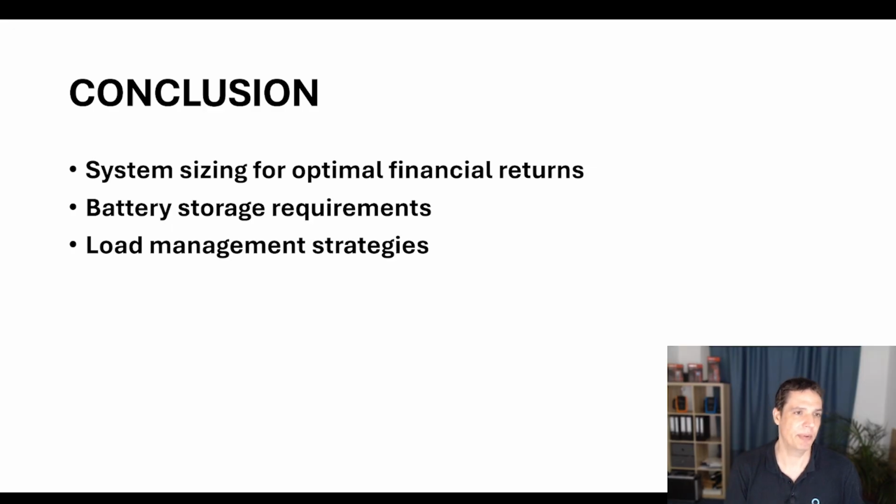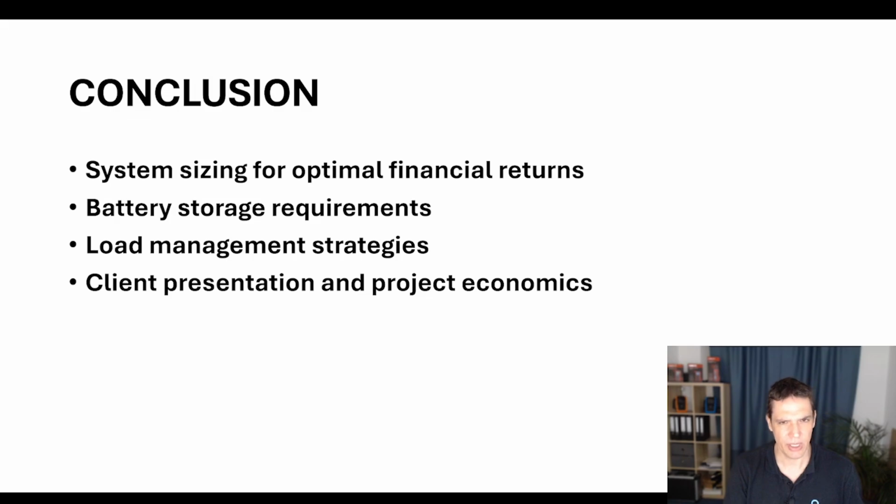You can implement load management strategies with building management systems or timers to increase your solar self-consumption. And also, having done these calculations, you can use it in client presentations, and you can optimize the project economics. And the client can see you've done your design based on actual data and not just on guesswork.